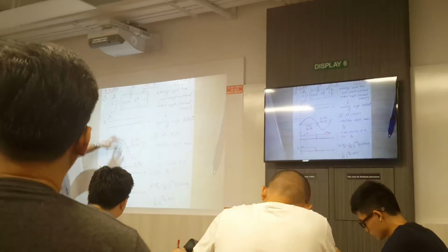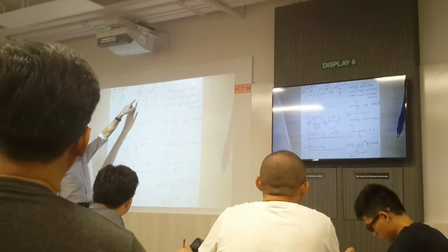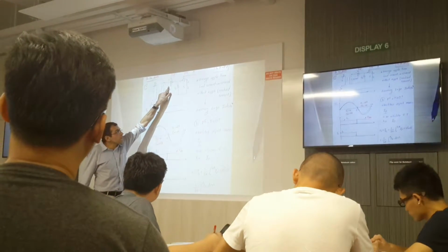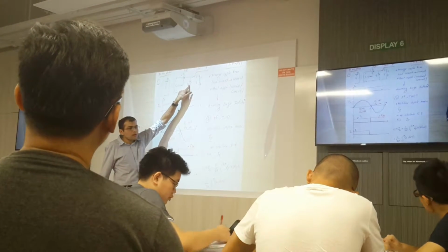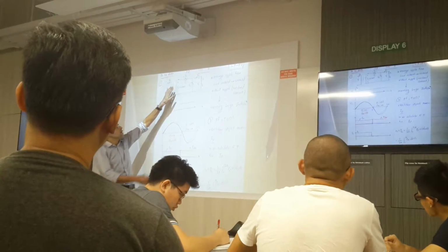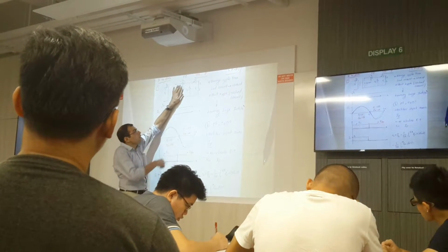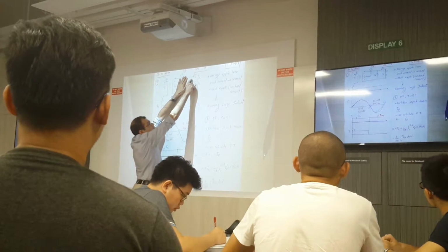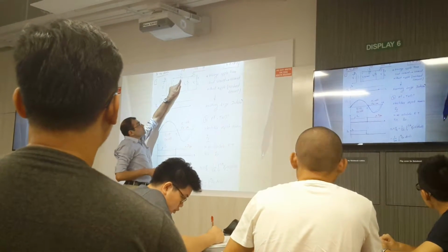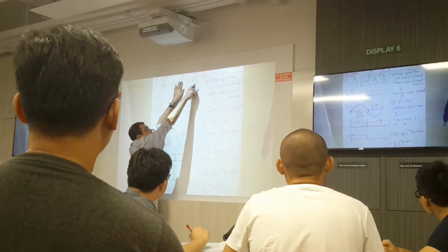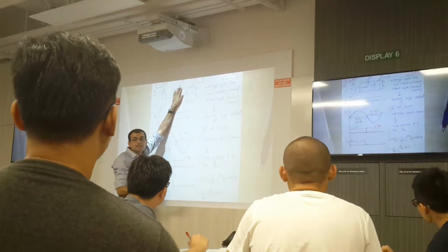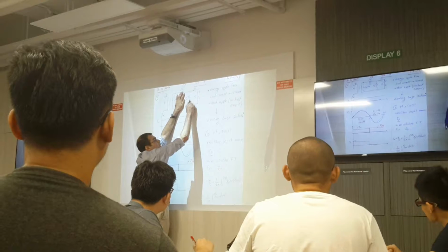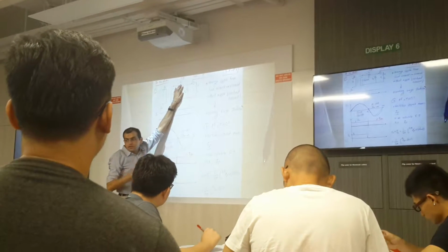For the second part, which is from pi to 2 pi, the input voltage is negative, therefore D1 becomes off and Dm becomes on. I told the reason. The reason is that once D1 becomes off, because of this inductor and this constant current which goes through this load and inductor, this current should continue flowing in some direction. So this current forces Dm to become on. So you understood the reason?